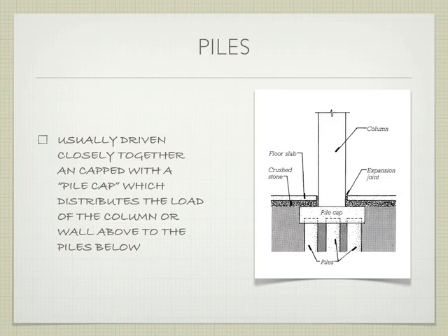So this is exactly what happened for the new span of the Bay Bridge, right? We needed the ability to make a foundation, right? Obviously, it's in the middle of the bay, so there's water in the way, which would be probably the most cohesionless material we could be working with, right? We can't drill through the water and have an air hole, right? It's not possible. So we need something. We can't pour concrete. We need some way of driving, right, from the surface down.